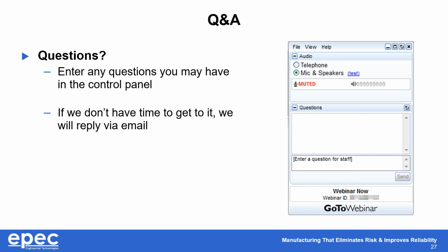And the answer to that is almost an unqualified yes. We've done many, many designs that existed as silver ink shielded designs and converted them over to EMI shielding film configurations, which provided the customer the benefit of improved mechanical bend reliability because of the thinner construction, and also reduced cost.